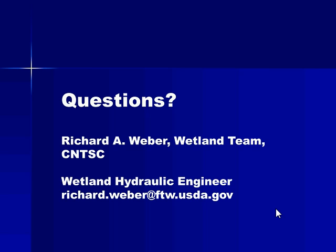What we can analyze with the toolbox we have is going to be based on the combination of lake gauge data, tide gauge data, stream gauge data, and whatever hydraulic structures or pathways we can model. And that's about the best we can do. That, coupled with evidence we can gain either from an on-site soils investigation or soils mapping, hopefully will be enough to get us going in the right direction.